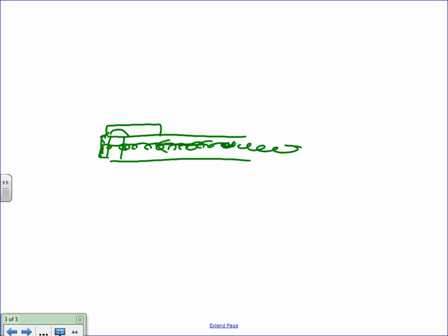This regular smoke detector senses that because the sampling tubes go into the smoke detector and take a sample of that air, and then that sends the alarm back to the fire alarm system that says this unit, duct smoke detector, has smoke inside the return duct.